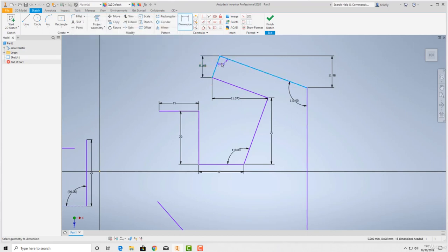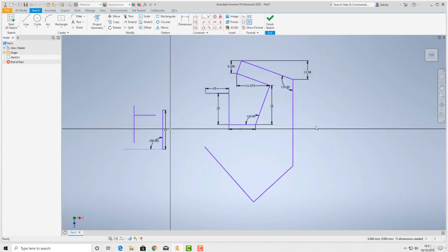And that kind of makes sense because you've told it that these two lines are parallel, and you've told it that this angle here is a right angle, is perpendicular. So this must be 90 degrees. Okay, it couldn't be anything else to keep these constraints you've already specified. So this is all fully constrained now, and you could go around, you could give more information here.